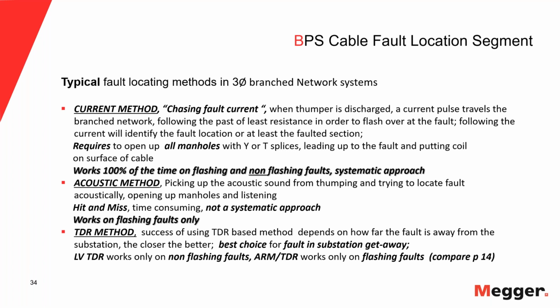And the good thing is it works for flashing faults or non-flashing faults. Even if I had a short circuit somewhere, when I put my thumper on, that current still goes through the cable. I still can pick that signal up. Okay, very, very important, because with the acoustic method, if I don't have a flashing fault, I hear nothing. So I can forget about it.